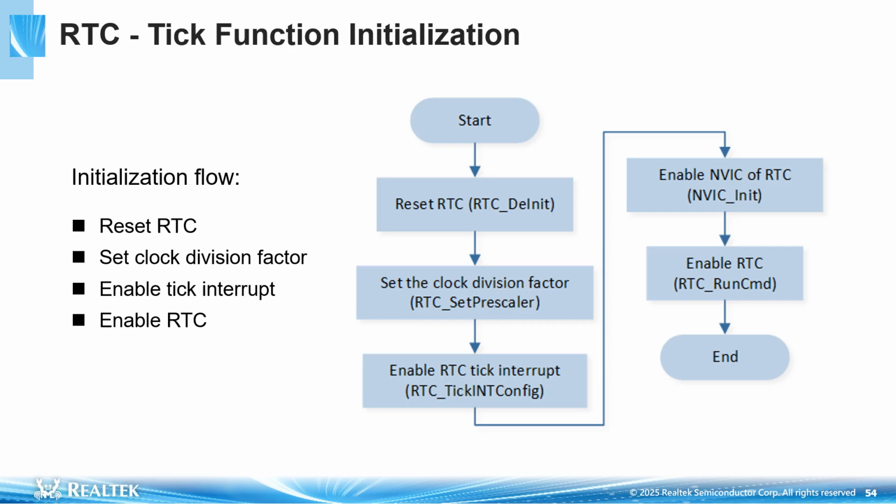The initialization flow of the RTC tick function is shown in the figure. First, reset the RTC, set the clock division factor of the RTC, then enable the RTC tick interrupt, and finally enable the RTC.